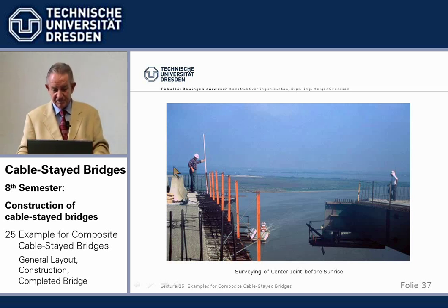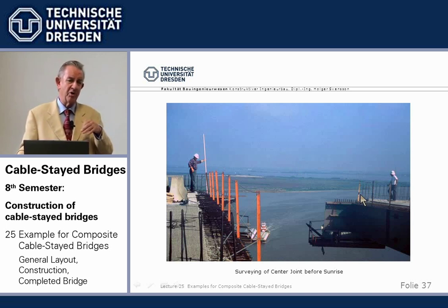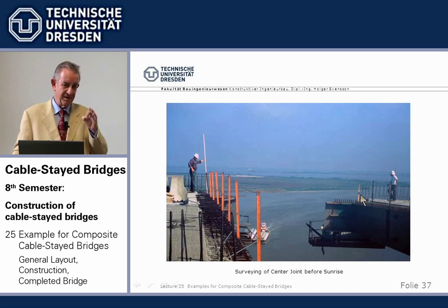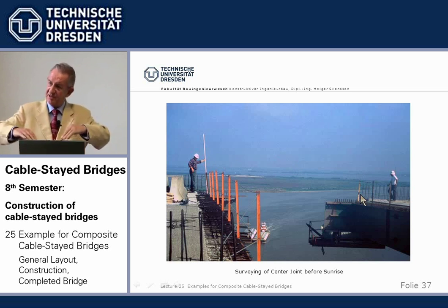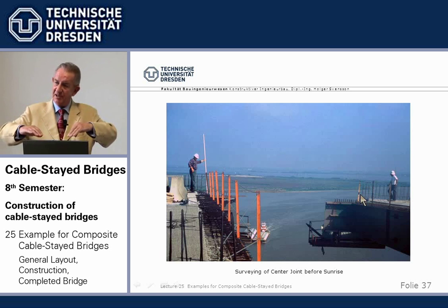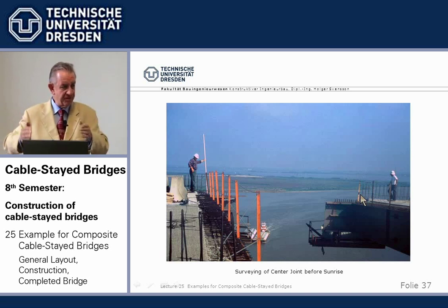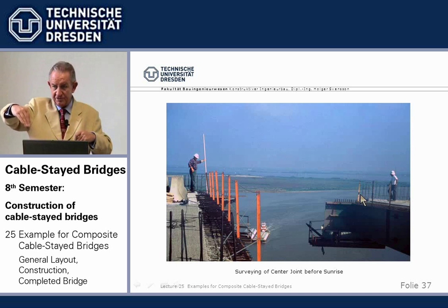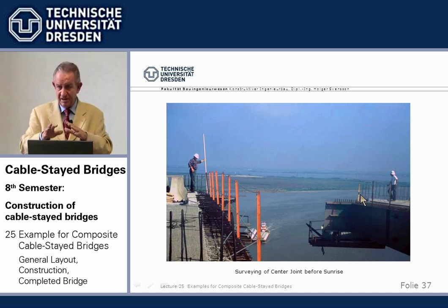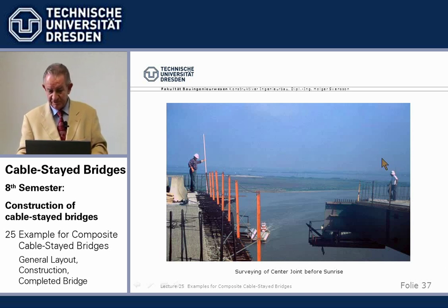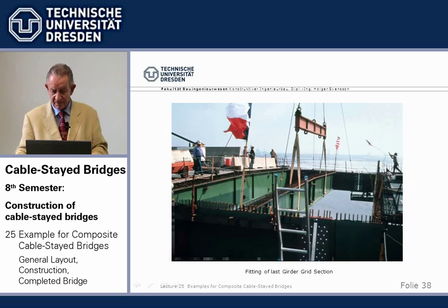So you have to survey very carefully, and you do that always very early in the morning, just before sunrise. Because then, especially in Texas with the hot sun, the non-uniform distribution of temperature from the sun hot on the deck, is even out as good as possible. And so this is in the morning just before sunrise. And here we lift up, flying the flag, of course the Texan flag, the last piece.